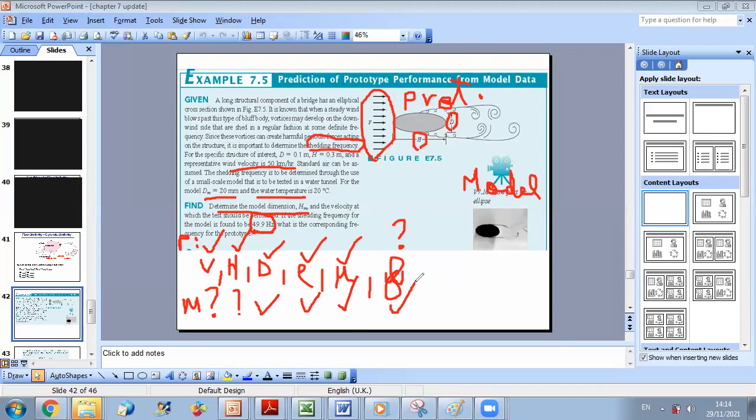So in total, how many unknowns do we have? We have 3. And this is a hint for you. You know why? Because if you have 3 unknowns to find, then you can deduce that you have 3 groups that can be formed with these variables. And we'll verify this together by performing the analysis to determine the dimensionless groups that can be formed to understand the behavior of the flow in this case.